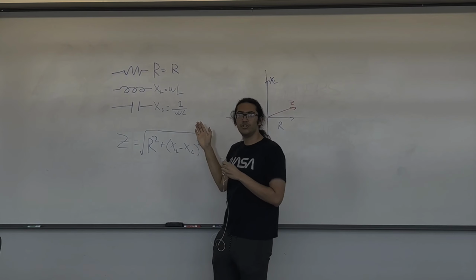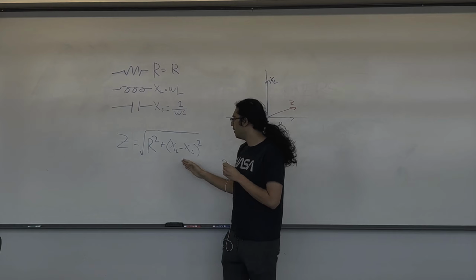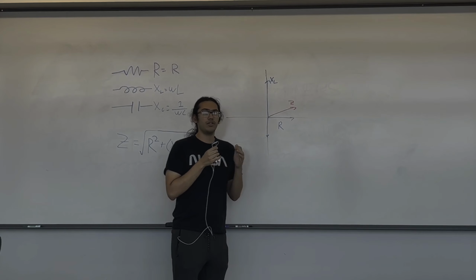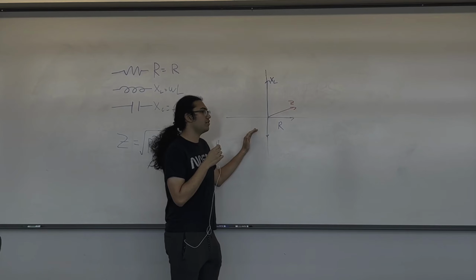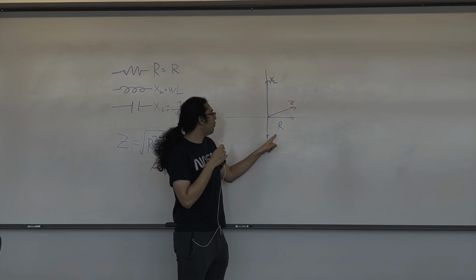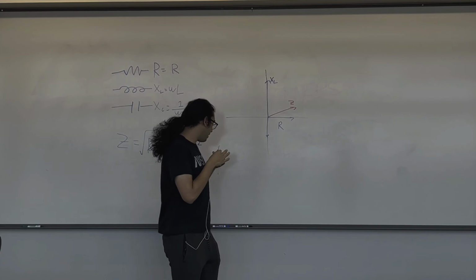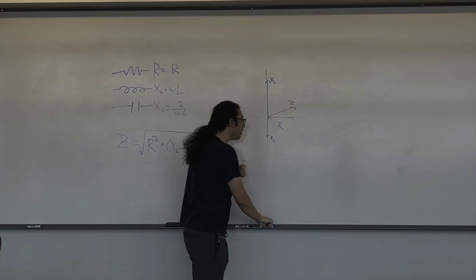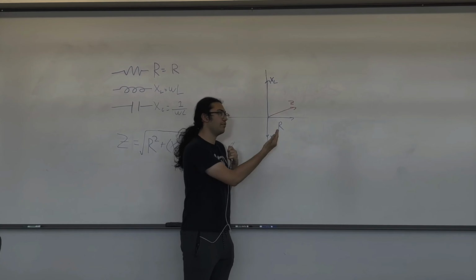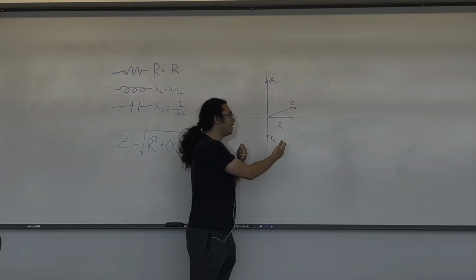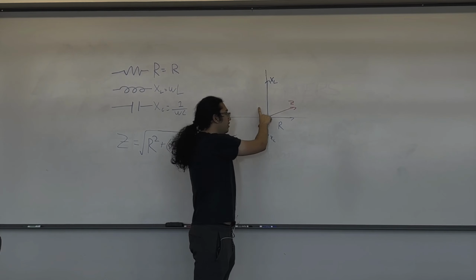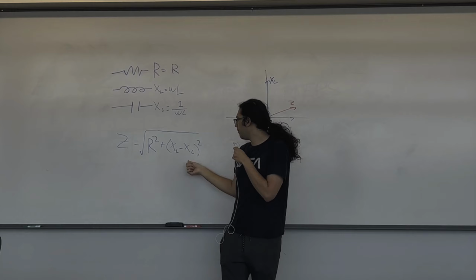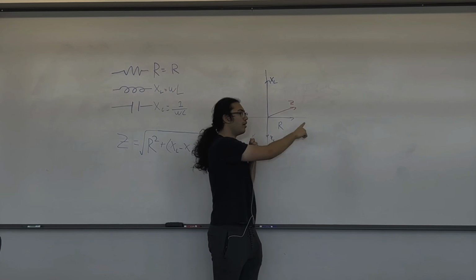So how do these all combine into impedance? Well, it's equal to this expression. Why this expression? Let's turn to our phasor diagram. On our phasor diagram, we draw these reactances as phasors on the phasor plane. R goes horizontally, XL points straight up, and XC goes straight down, which I forgot to label, but this is XC. When we want to find the total impedance, the combination of the resistance and the reactance, we do a vector sum of all these vectors. Since XL and XC point in opposite directions, they basically cancel out, leaving one vector pointing either up or down. That's why we have XL minus XC here. And then our resistance R just points out this way.